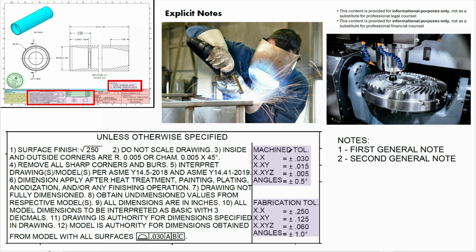Now, this in turn helps you reduce clutter and misinterpretation in your drawing numbers. So if you have a dimension called out with 2 decimal places, for example here, then the reader will go and see it's 2 decimal places. So this is the interpreted tolerance for that.